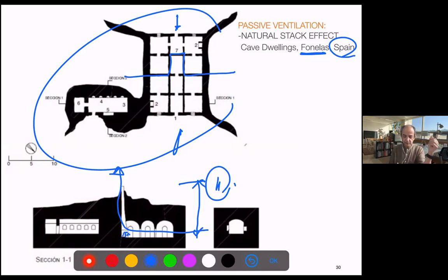So this is the place they use for cooking. It's great because you have the heat of the fire, but all the toxic gases go out, right? And that cooking also pushes more fresh air inside, because just the air going out makes a void. Just the difference of pressure, even if you have wind, will make the air come in. See how this also makes the obligation of having the rooms connected, right? So the air comes around, and surely there is another vertical opening in the bottom room.